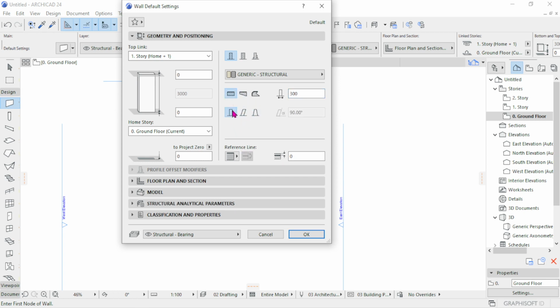So again, for the complexity, we have the straight, we have the slanted, and once you choose the slanted, you choose the angle of the slant. And of course, we have another one that is a bit tapered. For this one, you choose the thickness at the bottom. What is the thickness at the base? And then you choose the angle for one side and the angle for the other side, so that you can have a double slanted type of wall. Or you can decide to have one side at 90 degrees and the other side slanted. So that is the double slanted type of wall.